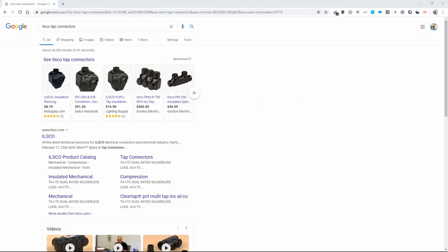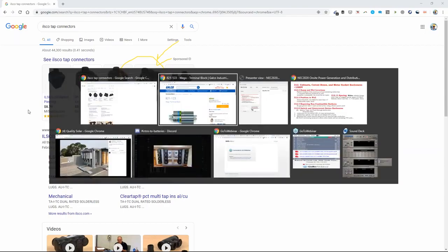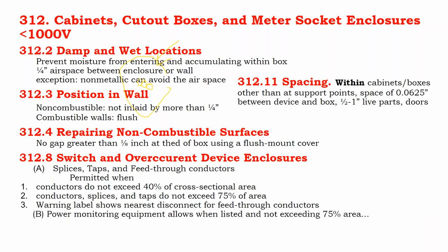Anyway, these knuckles take up space. They're larger than the cabling itself, and so what we see in National Electric Code is rules governing how large the box needs to be in order for you to not just pass the conductors through the box, but also to do work on them. And then also, the cross-sectional area of the entire box.